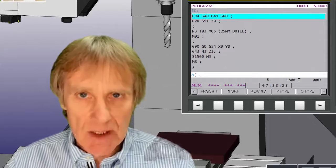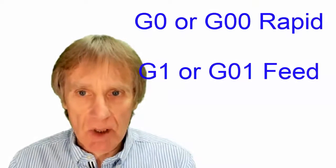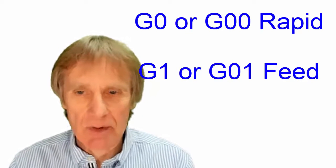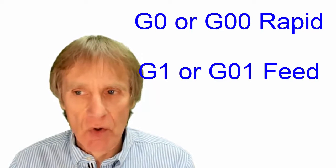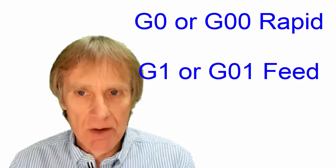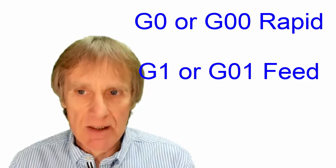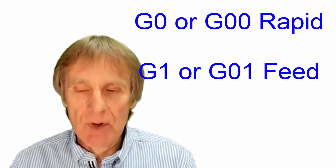So I'm going to use two basic G codes. The two basic G codes are G0, sometimes known as G00. Some people call it GOO or GO, which is not technically correct, but you will hear that said. This is a rapid move. It means that the machine is going to move absolutely flat out. So the motors just kick in at their maximum speed that they can go at, and the tool will arrive at its position in the quickest possible time. So all the axes that have been commanded with this G0 command will move quickly.